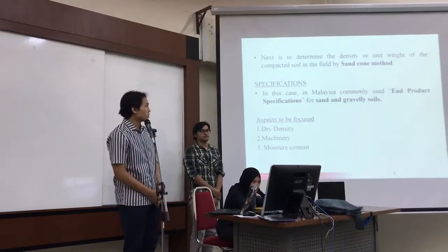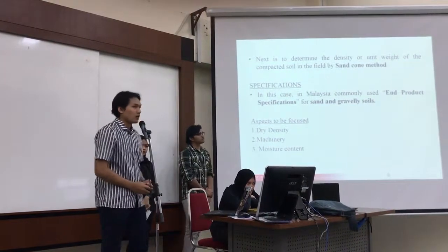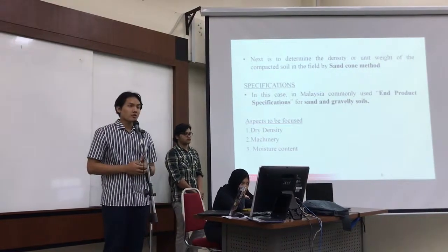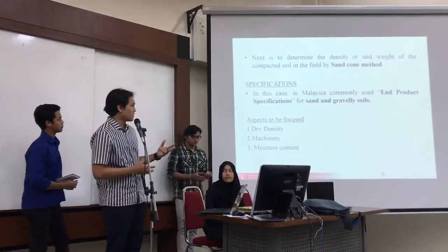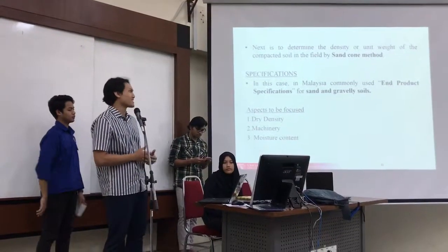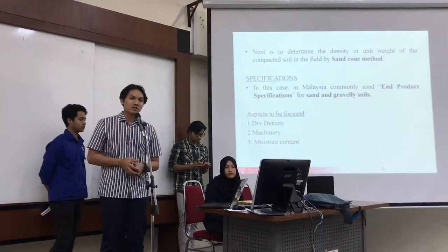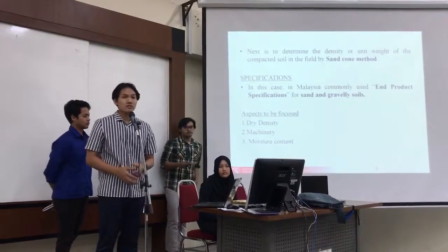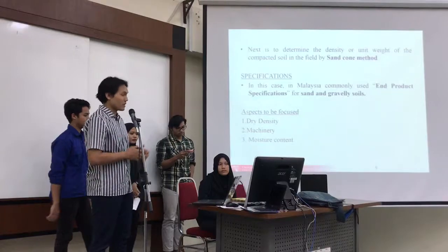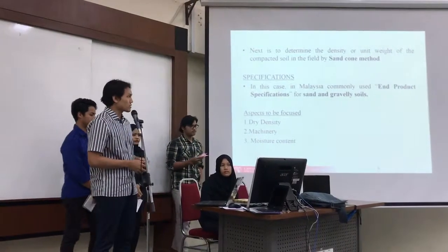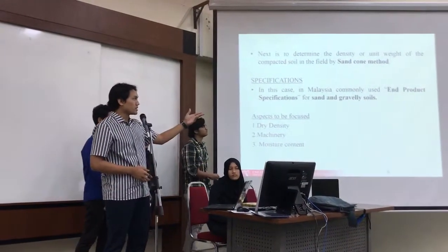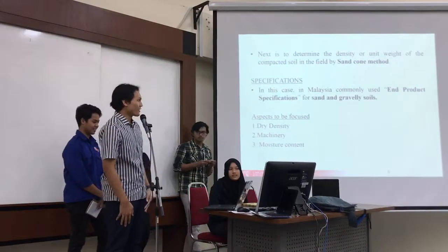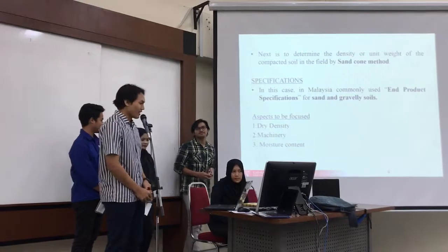Okay, next is for the specifications. For your information, there are 3 types of specifications commonly used in soil compaction: method specifications, end product specifications, and performance specifications. But in this case, in Malaysia, we commonly use end product specifications, which is specifically for sand and gravelly soils.